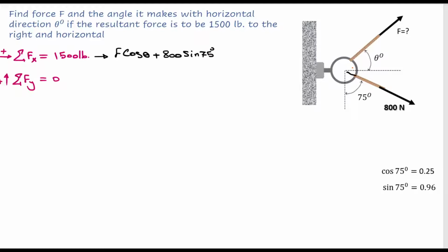Because if I consider this right triangle, the x component in this triangle is actually hypotenuse times the sine of angle 75. So this is 800 sine 75 degree. If you still have question about this, please watch the video about finding the components of vectors in my channel and learn it before going to solve this problem step by step.